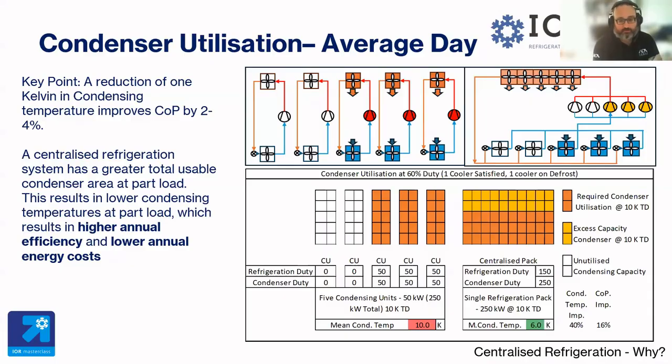And whilst we're talking about, in this particular case, a remote direct expansion refrigeration system, we should note that this centralization can be applied to water-cooled, ambient loop-cooled integrals, or as they might be referred to, semi-plugins, because they are still adopting, albeit an indirect, a centralized heat rejection surface.